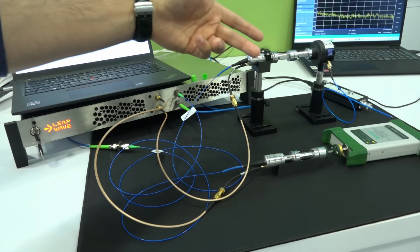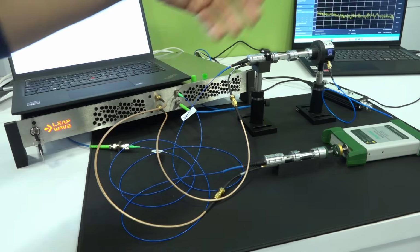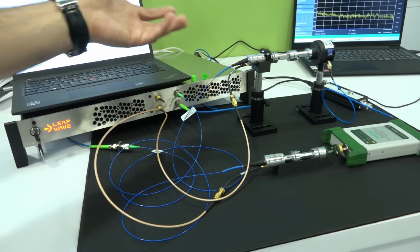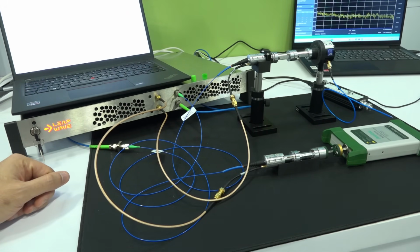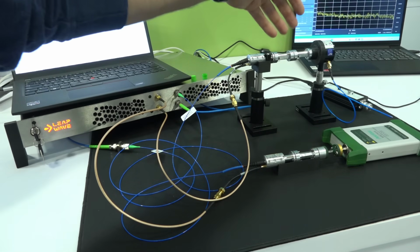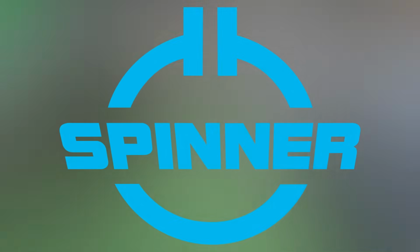Now on the other side, when you have two lasers, you can do coherent detection at the same time. So if you have a photodetector on the other side and then you can do the mixing, well, now you have a coherent link, just like we do coherent communication. Now you have this huge frequency range you can detect and analyze, and that's pretty interesting. A few innovations on the signal generation and the innovations on the transition can enable these kinds of systems.